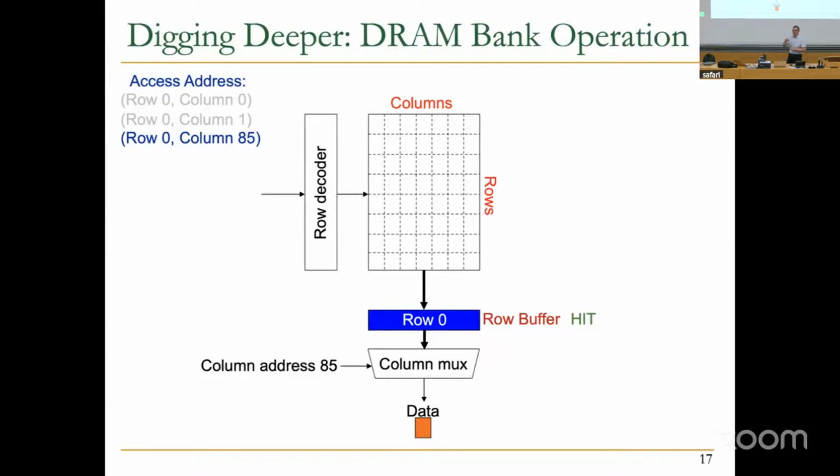Now, think of how a processor accesses data. Let's assume you're going through an array and your data is all mapped in the row buffer, the entire 2 kilobytes. If you're accessing every single byte, you first access 1 byte, column 0, column 1, column 2, column 3, and so on, until column 128 or so. Basically, you can go through all the elements that you're accessing, and except for the first one, they will all be row buffer hits. So the access will be faster because you have the structure called row buffer that's a cache.